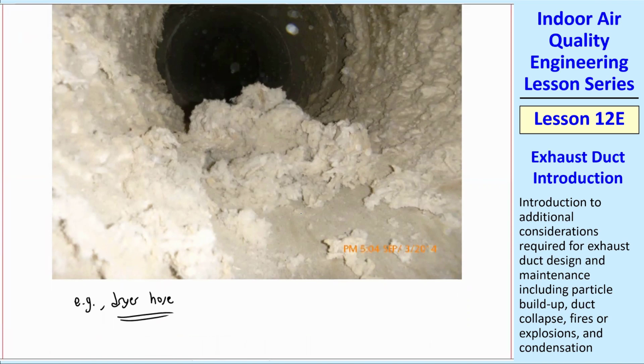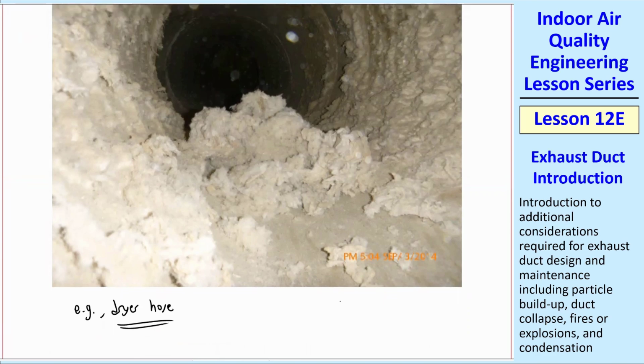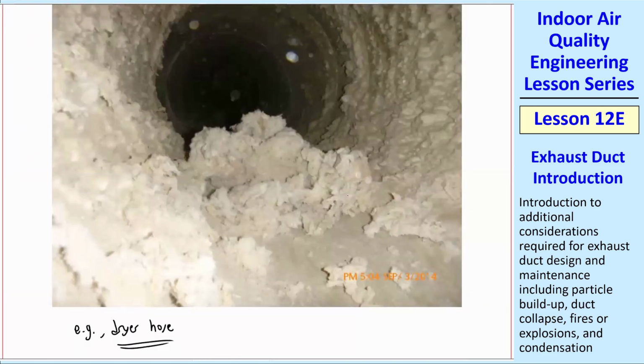My wife stands outside and can see all this lint coming out. We do that for a few minutes until the lint stops coming, and that way I just blow all that out. Again, if you don't do it, your dryer is going to have a harder time pushing the air through. Therefore, it slows down and gets much hotter than it should. It makes the dryer less efficient, and there are all kinds of problems that come with that.